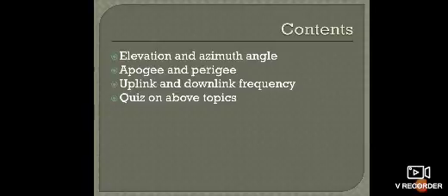So what is an elevation angle and what is an azimuth angle? They are referred to as the antenna look angles, based on the looking angles of the antenna. The elevation angle is the vertical angle formed between the direction of travel of an electromagnetic wave radiated from the earth station antenna, pointing directly towards a satellite, and the horizontal plane.